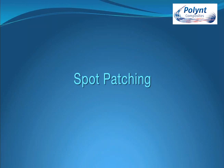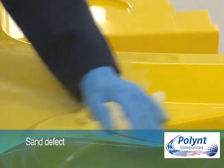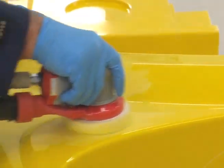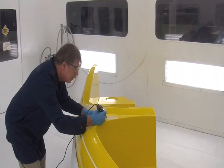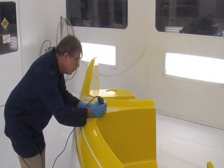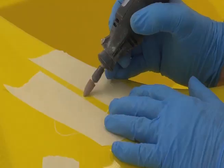Now let's look at spot patching. The patch should be close to the size of the defect. Sand the defect using a sanding block or dual action sander and large grit sandpaper such as 220 or 320 grit. If the defect goes into the laminate, you can use a router, pencil grinder or coarser sandpaper, 50 to 80 grit to grind out the material.